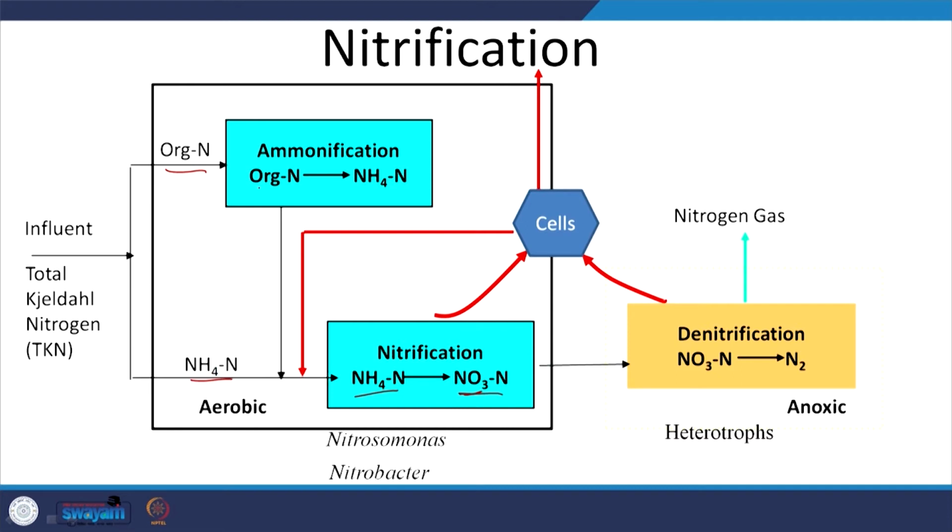And during that time, the organic N will be degraded by microbes to NH4, and then that NH4 again to NO3 minus. But as I mentioned, NO3 minus, or nitrate, is toxic to humans and you do not want it to be in the water. So, you have to remove it, but again it is very soluble. What do you want to do? You want to see to it that it changes phase such that we can remove it.